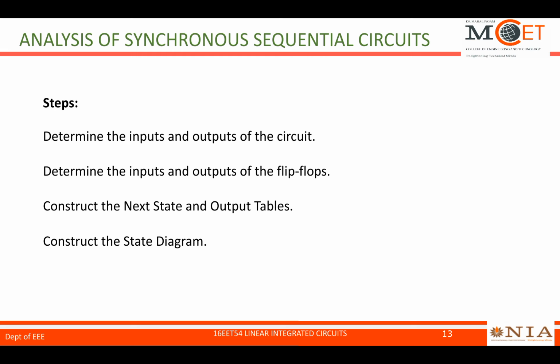We collect the inputs and outputs of the circuit and frame the expressions. From that we determine the inputs and outputs of the flip-flops. After determining that, we construct the state diagram, state table, output table, and so on.